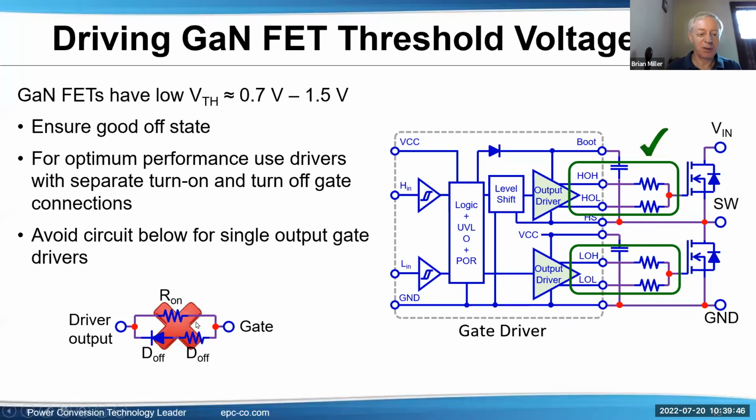It does come down to the gate threshold. Also, because of the speeds, diodes aren't diodes. Even with a Schottky diode, one of the EPC application engineers found that due to ESD structures, there's a little bit of reverse recovery in a so-called Schottky diode, in some of the small signal ones he looked at.